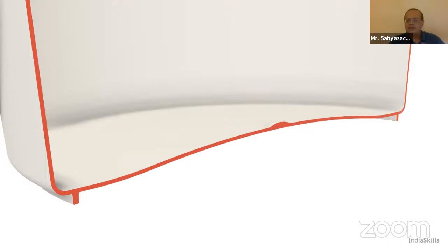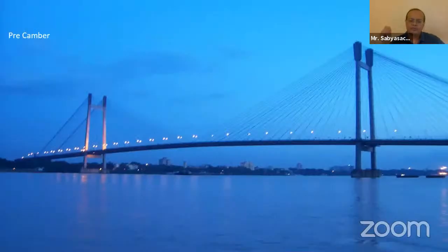It's there because the entire weight of the water, say about 15 liters or so, so that's 15 kgs of water weight, is actually coming on the bottom. And if it's not pre-cambered, which means it's not domed, it will sag. Try and see wherever you're seeing something of this sort. I'll give you an example. Look at a bridge. Look at the deck of the bridge. Do you find the deck of the bridge flat?